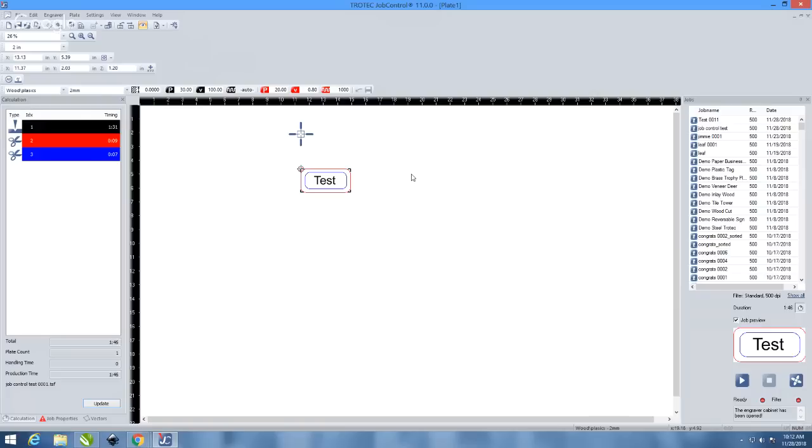Right, so here's a feature. If for whatever reason, maybe you had your material settings entered incorrectly, and when you ran your job, your material didn't get cut all the way through. Before picking it up and moving it around, if you could tell that it hasn't cut through, come here and you can repeat your cut lines. By selecting this, it'll run the job again, ignoring any engraving.